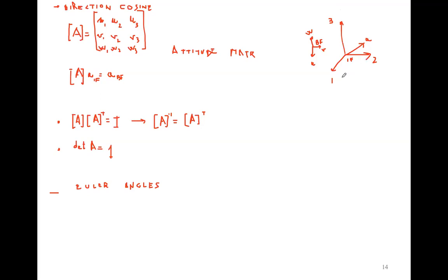These 6 types of rotations, if you commute all the indices, represent a rotation about each of the main principal axes. However, you can also try, for example, a rotation through 2, 1, 2 or 1, 2, 1. So this kind of rotation repeats one of the indices. That sometimes enables the possibility to avoid the singularities.